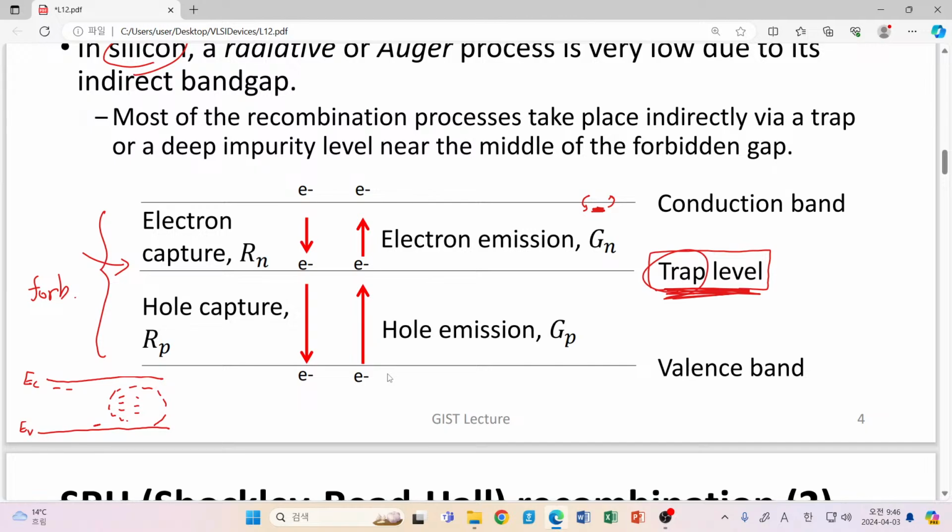Then for this one, interaction with the valence band is almost impossible because this is just on the order of several milli-electron volts. So the energetic distance between the valence band and this N-type dopant state is close to 1.0 electron volt or even higher. Since the energy is too different, it is almost impossible for an electron occupying this state to go that way. This is not allowed.